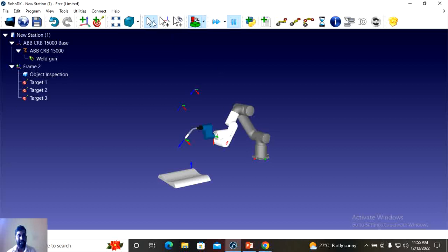And this one, don't move reference frames, objects, tools. So these things should not move. If you press like this, it will not move. And if you press this one, see this key, move reference frames keeping the relative positions with child items. Or you can do this operation by pressing alt also.